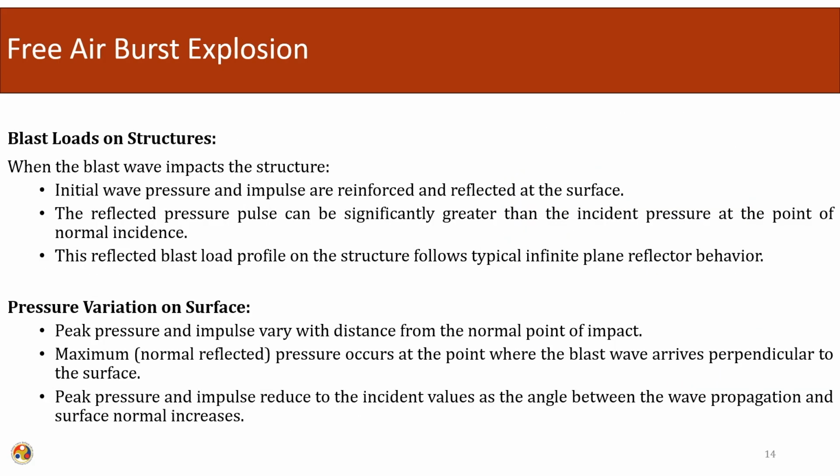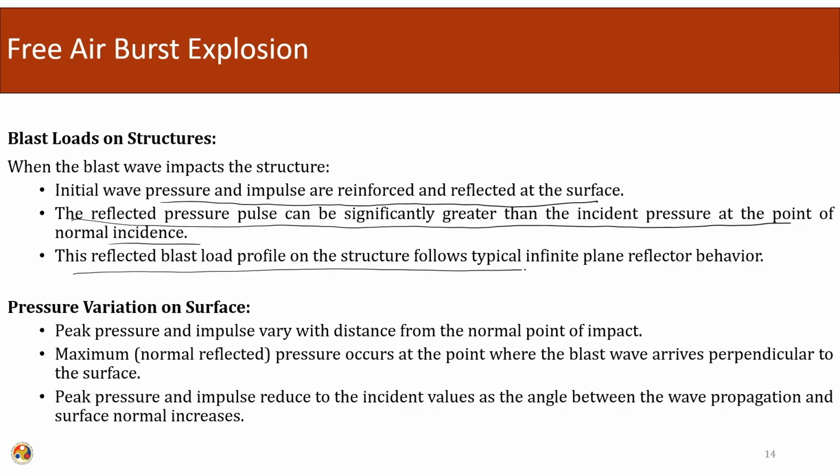So, in a free air burst explosion, when the blast wave impacts the structure, the initial wave pressure and impulse are reinforced and reflected at the surface. The reflected pressure pulse can be significantly greater than the incident pressure at the point of normal incidence. This reflected blast load profile on the structure follows typical infinite plane reflective behavior.